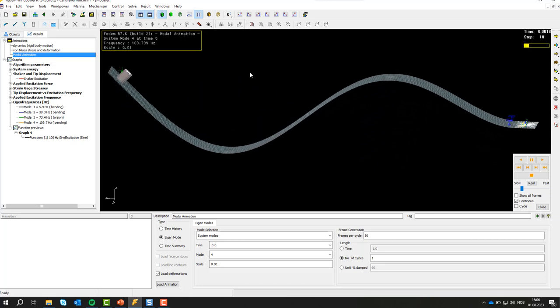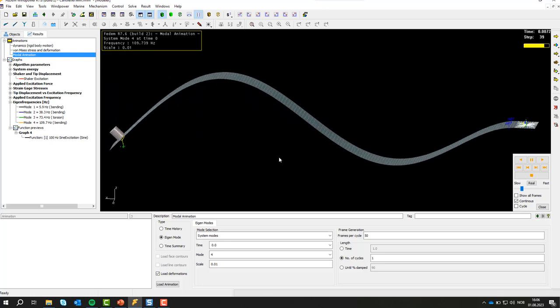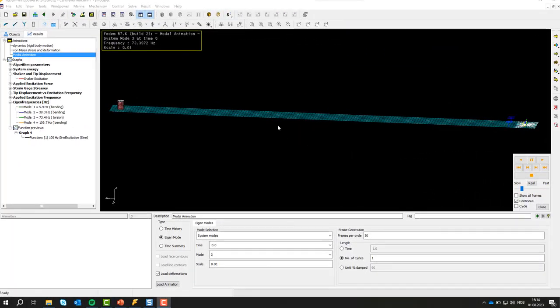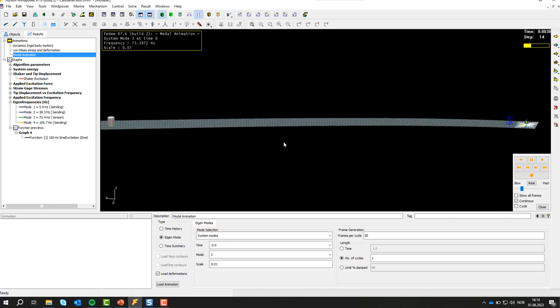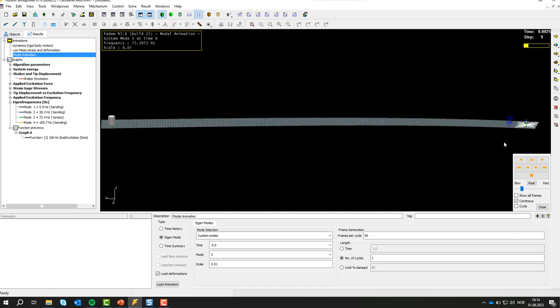There are some small deviations which probably causes the additional mass of the wires which are connecting the accelerometer to the test rig. You might have observed that FEDEM is also giving an additional Eigen frequency at 73 Hz. And this Eigen frequency was not observed in the resonances at the physical test. And the reason is simply that the excitation direction was in the vertical direction. And this mode shape is in the horizontal plane. So in the physical test, we couldn't observe this motion. We would have observed it if the excitation was in the horizontal plane.